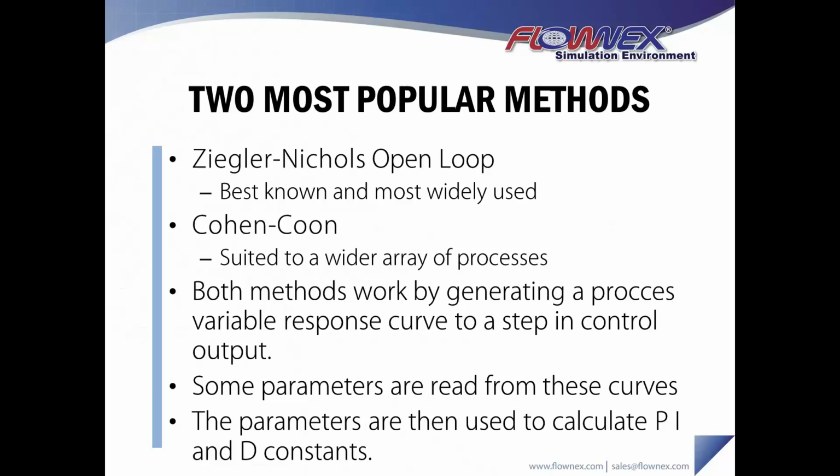Both of these methods work by generating a response curve from a step input in your control output. Some parameters are read from these curves and then used in calculations to determine the P, I, and D constants.